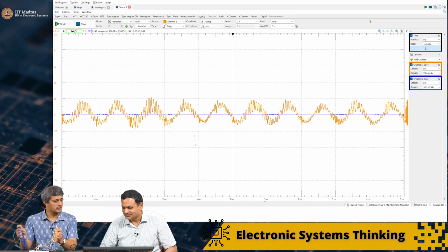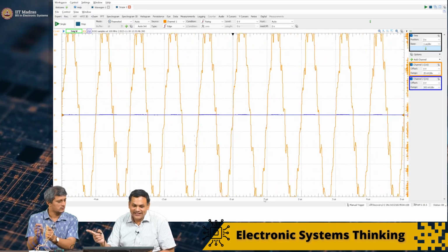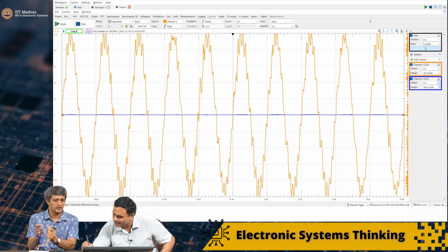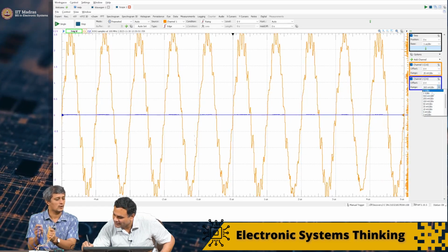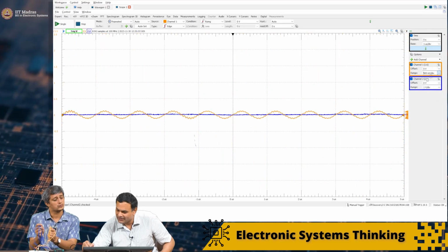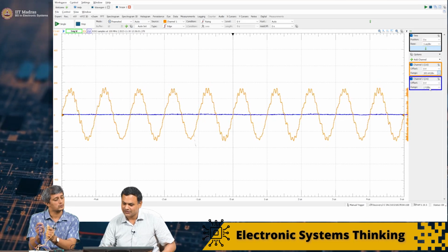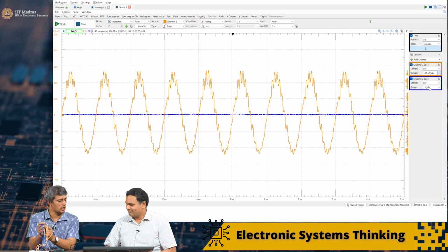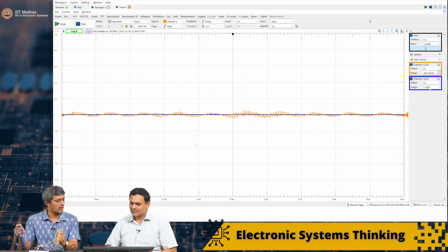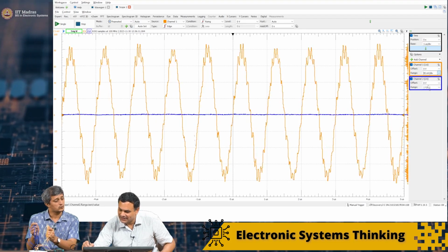What I'm doing is bringing the transmitter and receiver closer and closer. This is inductive coupling. Let us say 1 volt per division, and I'll make this 500 millivolts per division, or let's say 100 millivolts per division. I brought it really close. This is purely inductive coupling. And then I take it far away, and then it's gone.